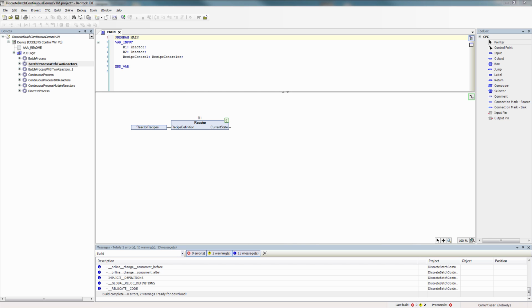As mentioned many times in this demo, the power of the Bedrock IDE and OPC-UA provide unprecedented integration between control and HMI. In this case, to connect an Ignition reactor template to a Bedrock Ignition function block, all we need to do is add a new instance of the reactor data type from the library, give the new instance the name of the Bedrock reactor function block instance, and drag the fully functional template into our main screen.